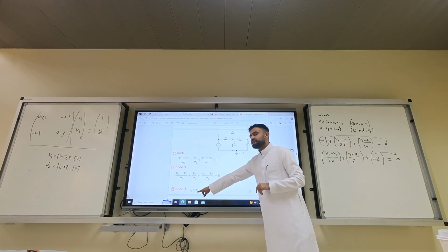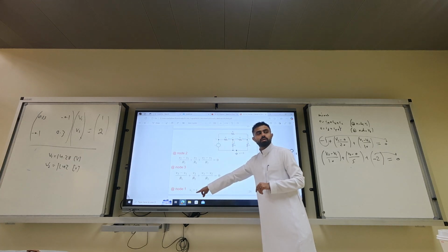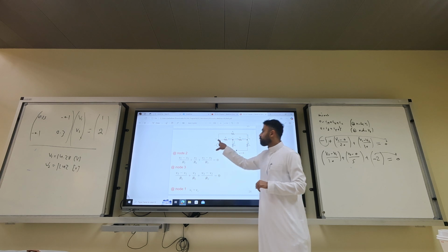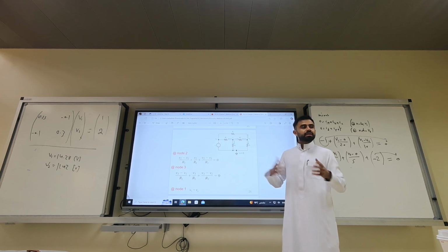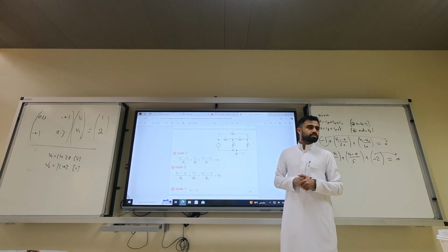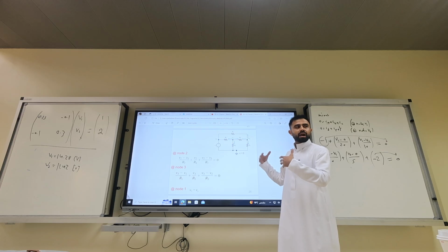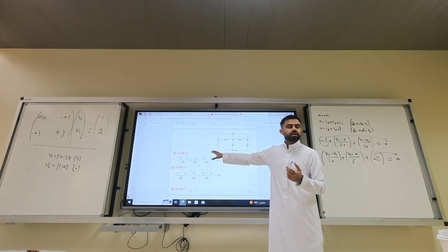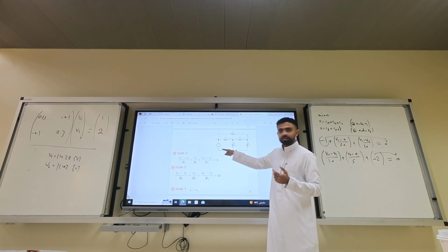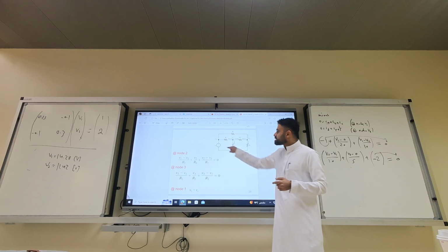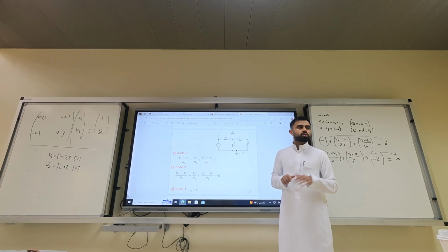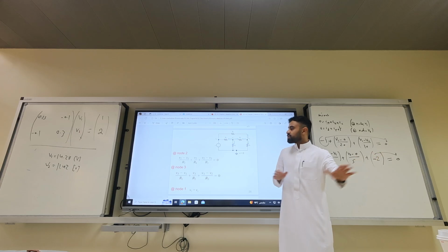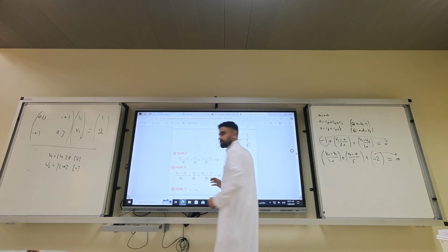Do I need to include this equation in the standard form? No, we have 2 unknowns. We already know VS. Okay. Do you know R2? No. It's the same thing. This is just a problem that deals with variables, but in reality, you do not include VS here because you cannot calculate the current here. There is no resistor where you can divide over. So do not include it in the standard form. So the standard form includes only 2 equations.